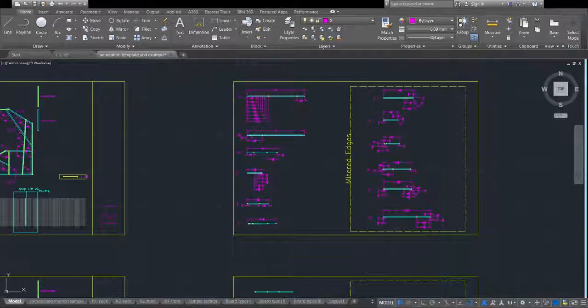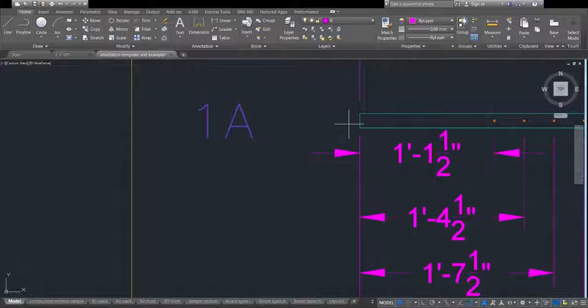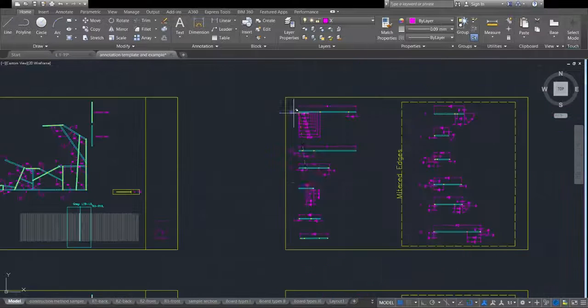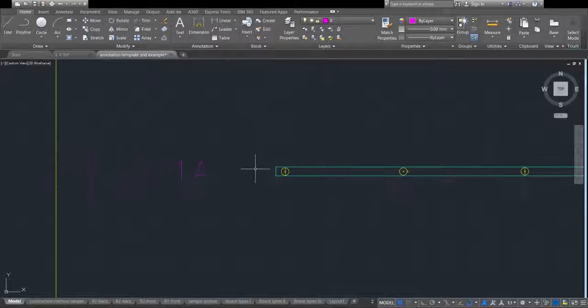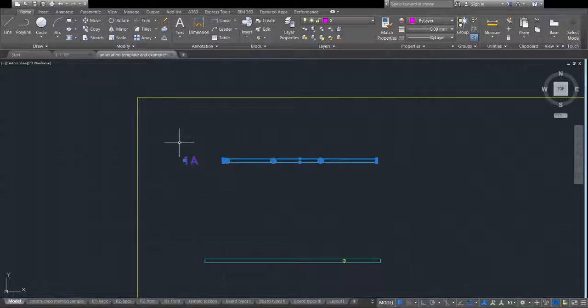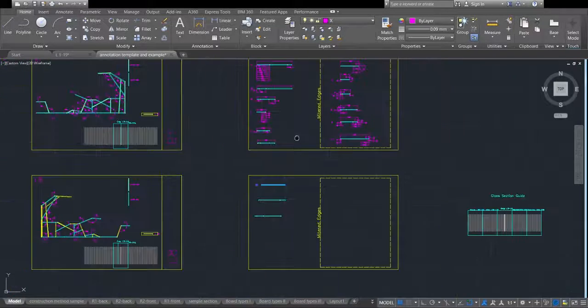First, I'm actually going to put a label on it. So the way that I've been doing this is I just grab the label and then copy it from the middle of that beam to the middle of this beam. And then this also kind of helps us position. Oh my gosh. So sometimes AutoCAD goes so slow that you type too fast for it, and so you can hit MOVE enter and it'll interpret your command as MO.